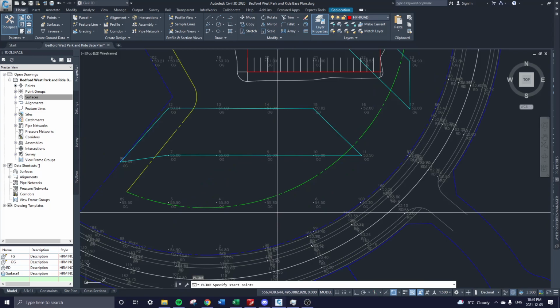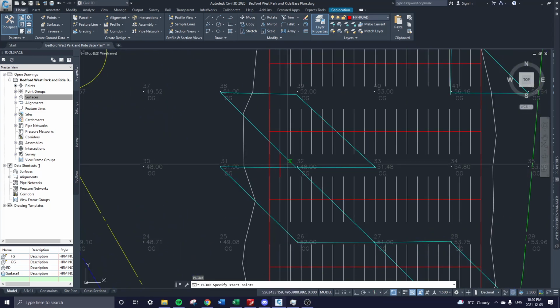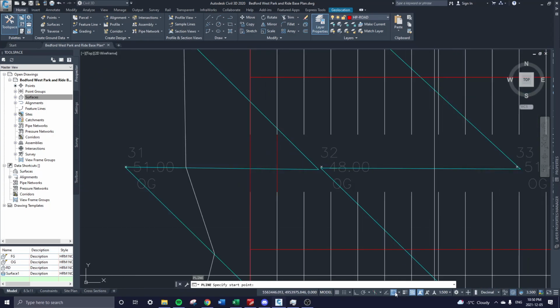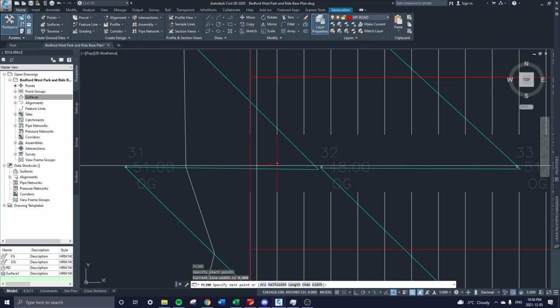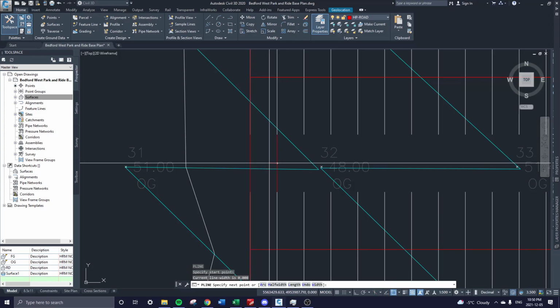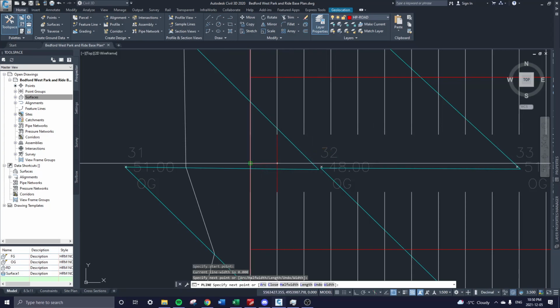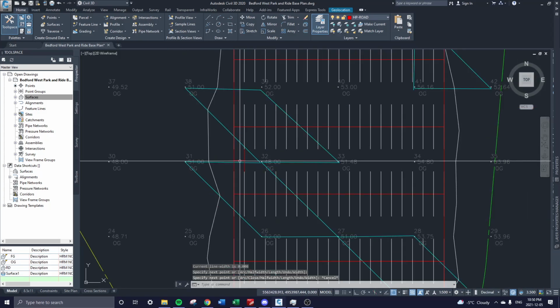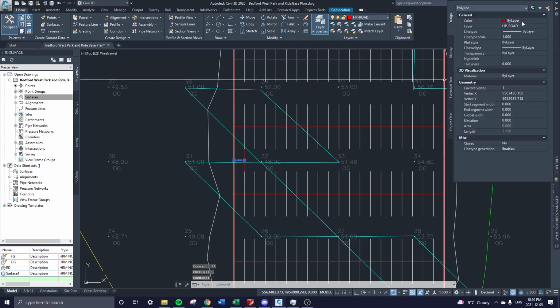To do that, you see how I drew just a polyline between these two lanes? If you have midpoint selected in your grip there, it's down here, hit that arrow, midpoint, you can select the middle of that line, and I'm going to draw a line from the middle of this laneway perpendicular to it, and I'm going to make this another color.